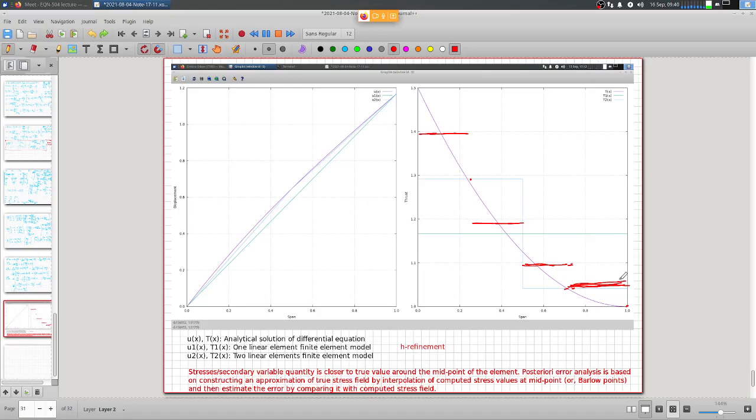But initially we took care of boundary conditions, so I thought that it should be improved. Yes, we imposed the boundary condition on du by dx, right? So let me just say, this is the approximation, that is AE times du by dx over element number 1, and this is the approximation AE du by dx for element number 2.